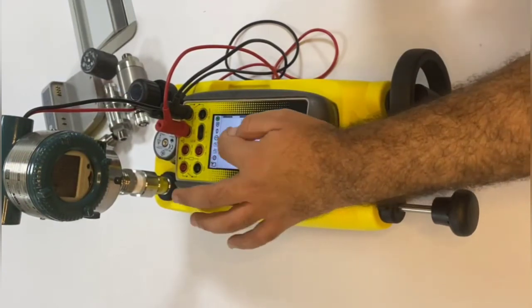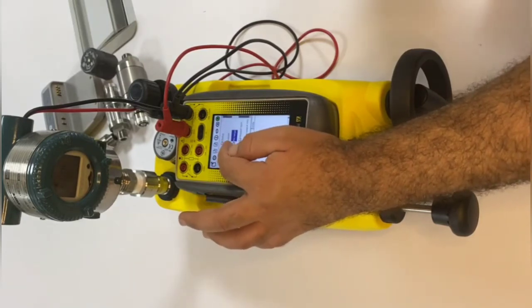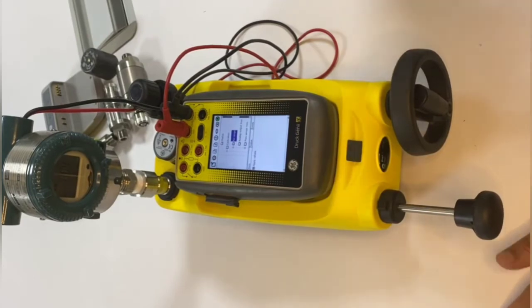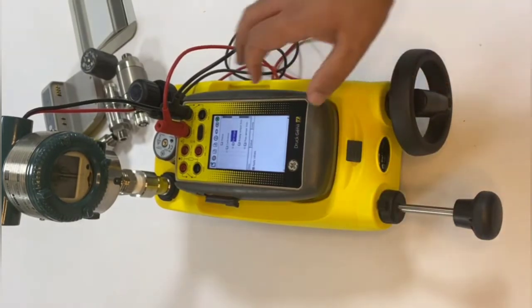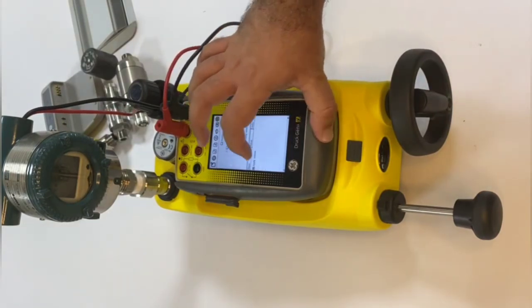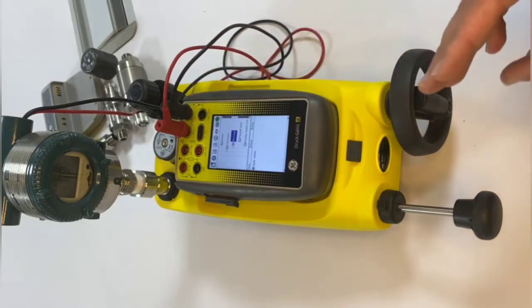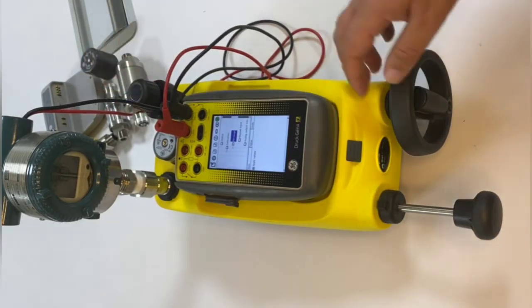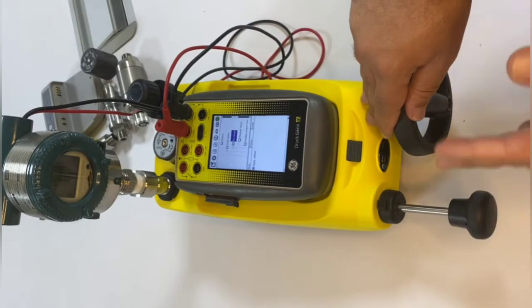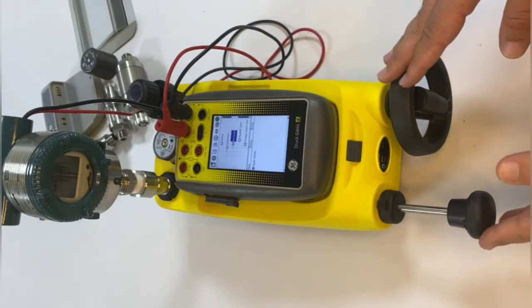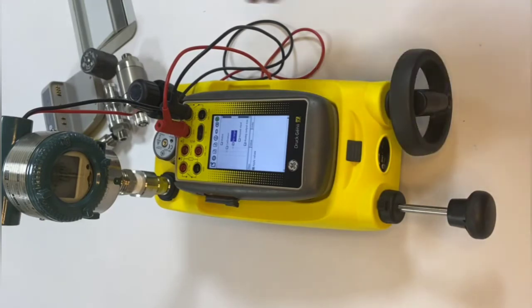Calibration. In calibration, we have the rerange, which we have did before. And by the way, you can perform a calibration and adjustment at the same time, thanks you have a calibrator and communicator at the same time. So instead of doing the keypad input for LRV and URV, you can put apply values, the device telling you to go to 0 or the LRV, then you use the calibrator to go to 0, then go to URV, you can pressurize 40 bar like what we did, then you perform calibration and adjustment at the same time. This will save a lot rather than keep connecting calibrator, communicator, calibrator, loop calibrator. You have everything in one kit.